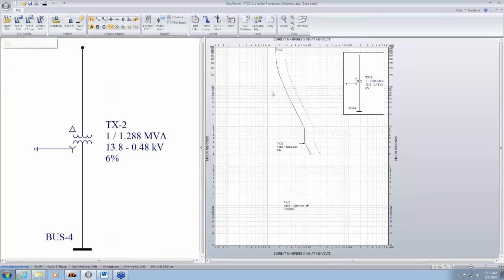So that's a transformer damage curve. The top section where we have this little bit of curvature here, that is the thermal overload damage curve, and towards the bottom is your high fault current, a lot of magnetic stresses, and that's the damage curve for that. Let's take a look at some of the options for the damage curve.